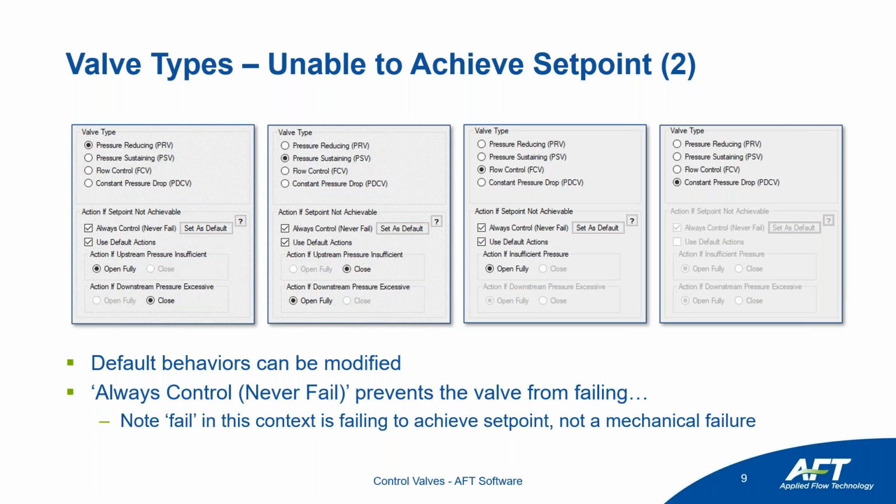So if we have a flow control valve, and again, it can't reduce the flow to its intended set point, I would say that the control valve has failed open. It's not necessarily that there's a physical issue with the component, that it's, again, not a mechanical failure necessarily.